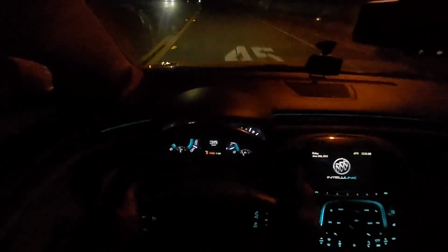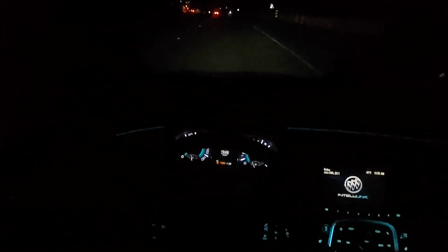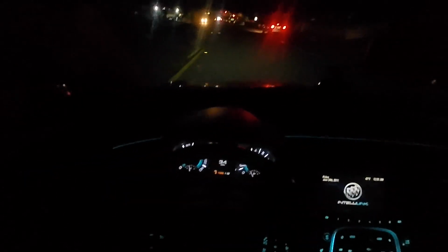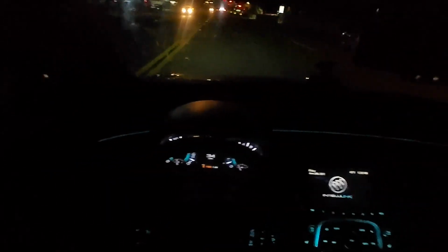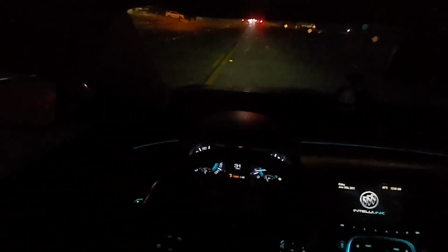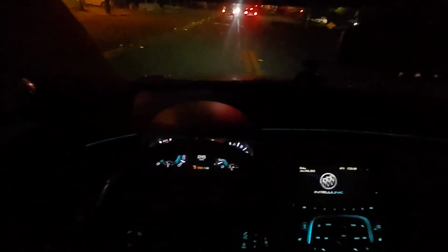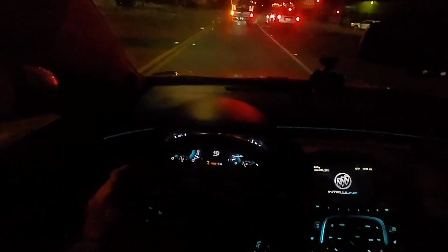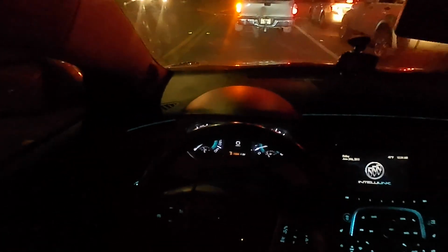As you can see, we don't have any codes on the dashboard. It's all cleared out. The car seems to be smooth, except, like I said, we did change the spark plug, so we do have a little bit of smoke. This should clear within a couple of miles. And right now I'm gonna try to take it on the highway and see if we can duplicate the issue where we have the flashing check engine light and the StabiliTrak warning, or if the problem is completely resolved.